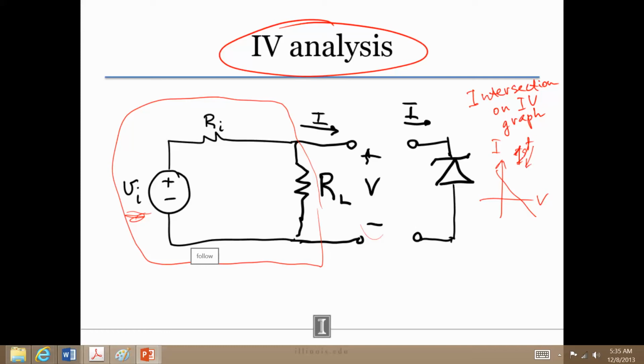All right. In this case, the Zener diode here. Notice the current flows into the way we defined it here, flows into its positive terminal. All right, and in the first quadrant, this Zener diode is going to be a load, and we know it's going to look kind of like a regular diode, but this is going to be its V_Z breakdown. And so where these two curves intersect, that's the operating point. Notice that this V Zener is only supported for this positive current, right?